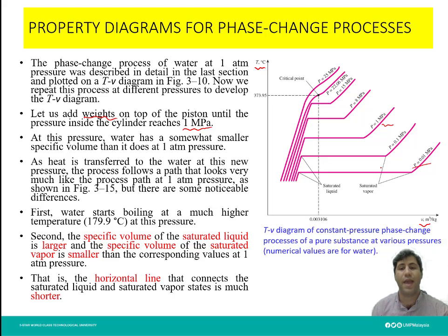Now we will see why we have something like this. This is because of the saturation temperature and pressure which I already introduced to you. But let's see the similarity. Again, we have those regions: subcooled, saturated liquid, saturated vapor, and superheated area. Again, we have all of those areas. Here is the superheated area. You can see this is for a different pressure. As long as the pressure is increased, this graph is shifted upward.